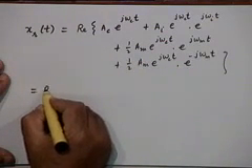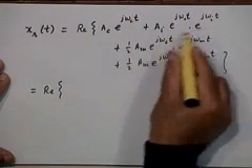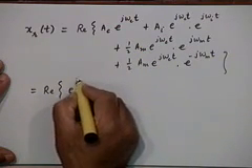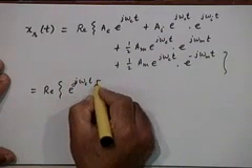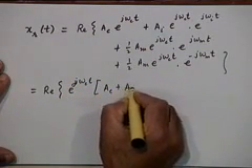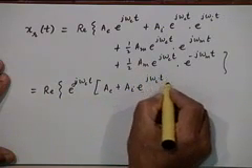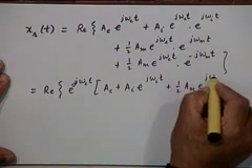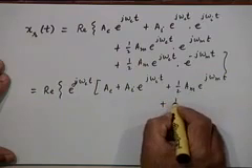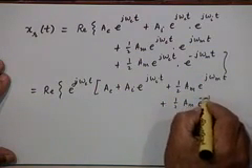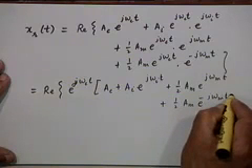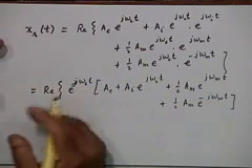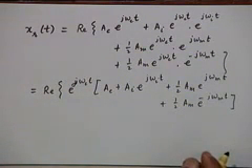which you can write as the real part of, take the e^(j omega_c t) term out common, because that is present in every one of these terms: A_c plus A_I e^(j omega_I t) plus half A_m e^(j omega_m t) plus half A_m e^(minus j omega_m t). And we would like to represent this signal x_r(t) in terms of a phasor diagram. Do you know how to do that?